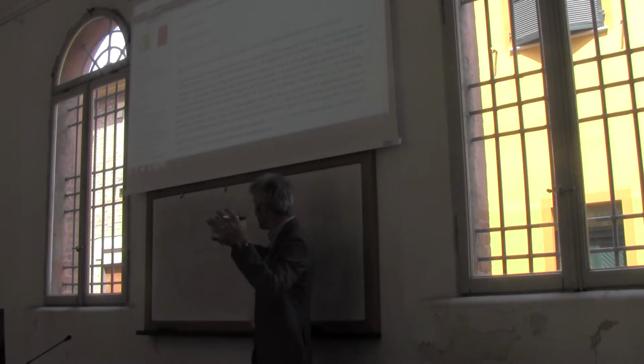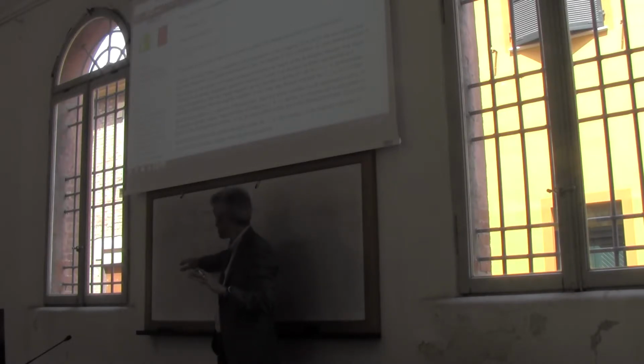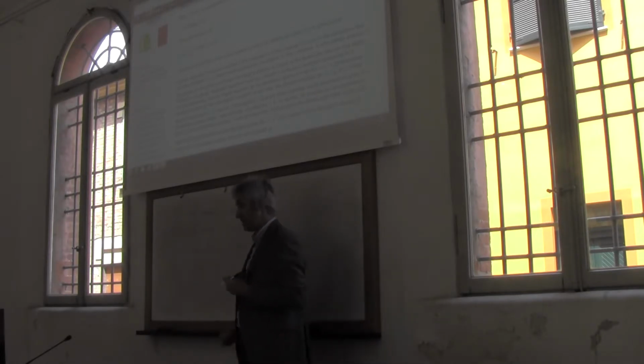If you basically have n physical parameters that can be used to describe the process, and they depend on 3 units, and you make these parameters dimensionless by combining them, then it's understandable by intuition that you reduce your number of physical parameters to a reduced number, which is n, the number of physical parameters, minus the number of the units. Okay, in this case, let's move forward, let's apply it here.